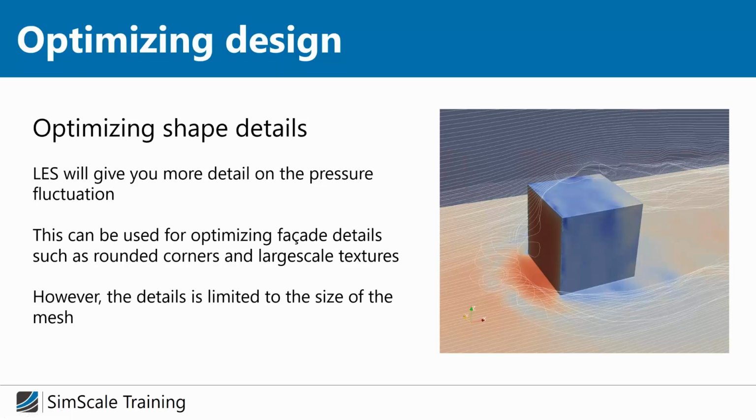And you can see if you introduce some roughness on your facade, then you can reduce the eddy development. You can have some kind of spoilers that direct the eddies in some direction, and that is doable, and it is quite a bit more computationally demanding than the simpler models, but you can definitely do that.